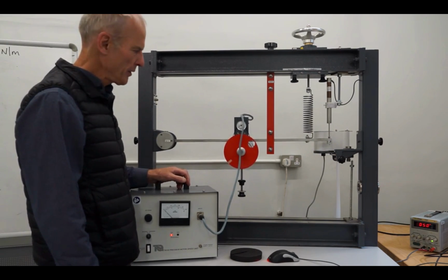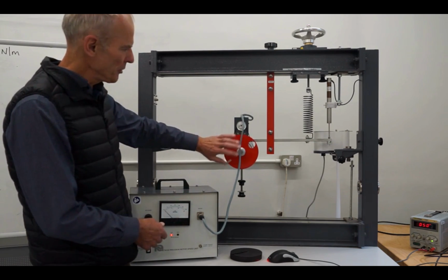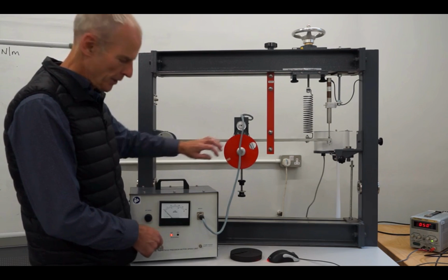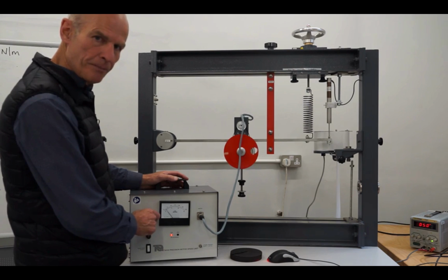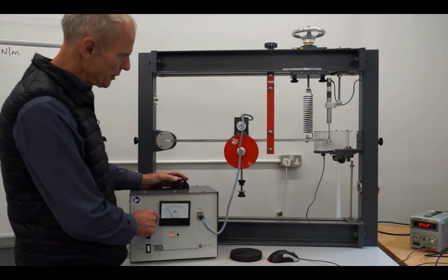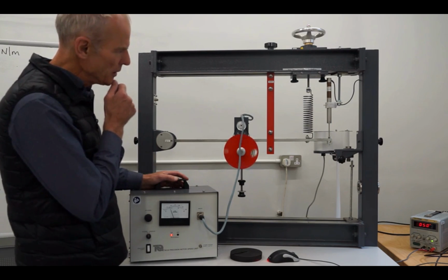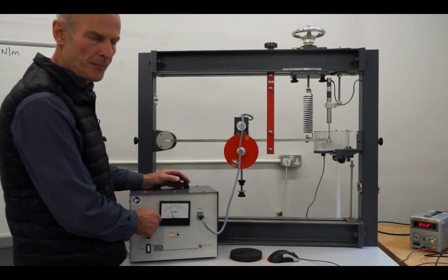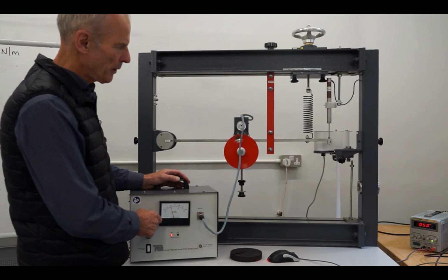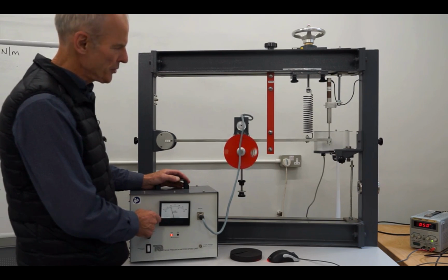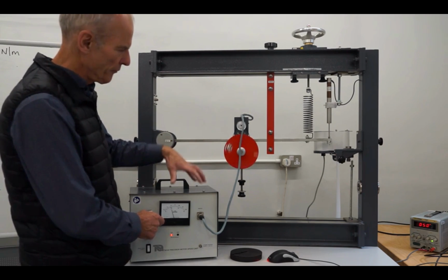The next step, having got the natural frequency, is that we apply the forcing frequency, which means that we're going to basically spin this up. We spin this up with this box here. We twiddle this knob, and you can see that not much is happening. As you twiddle it up, at some point you can see this is starting to rock up and down. This is called harmonic excitation. The frequency at which this is going round is the frequency of the forcing.